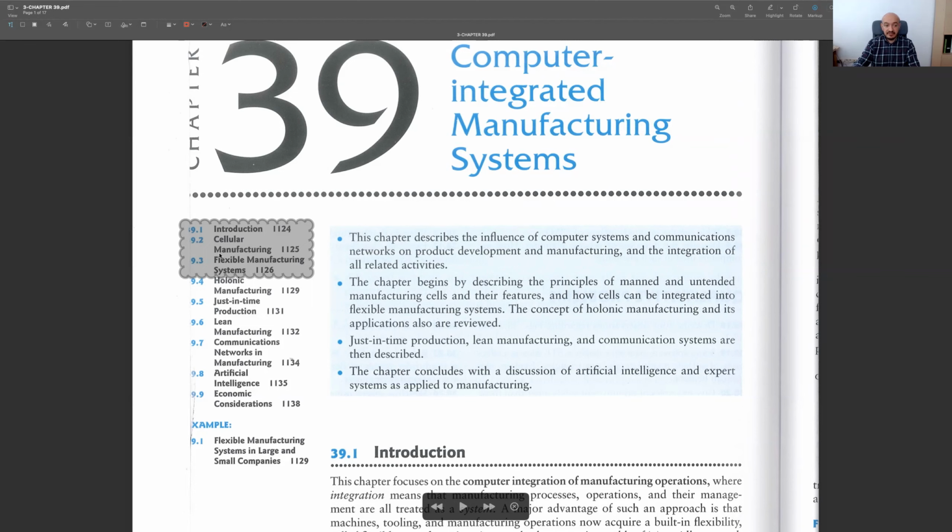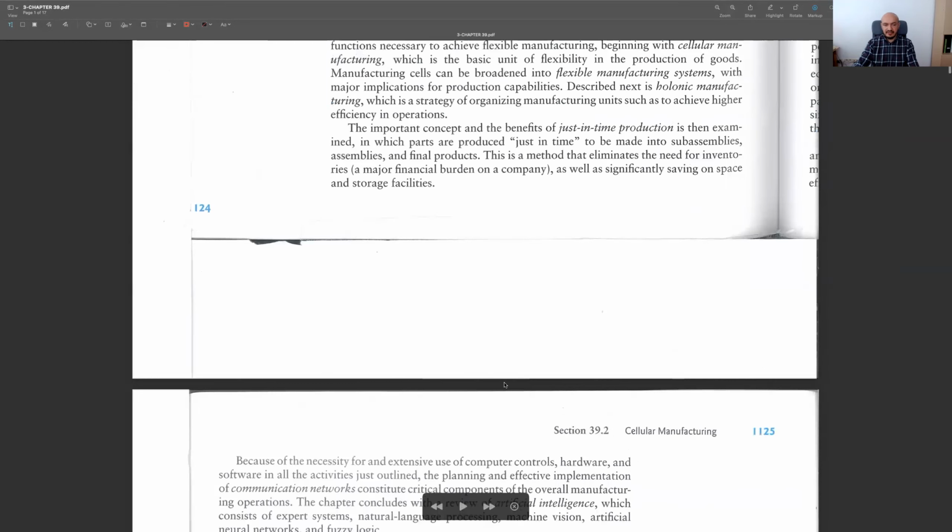The first one is cellular manufacturing, in which we have a cell, a kind of a room. We have seen an example in the production of Apple Mac Pro. If you remember, there was a cell, and at the center of that cell, we have seen a robot, and the robot was responsible for carrying items from one unit to another unit, or carrying the items and putting them onto the conveyor belt. So it's an example of cellular manufacturing, but flexible manufacturing systems are a bit different. These are much larger systems compared to the cellular manufacturing systems.